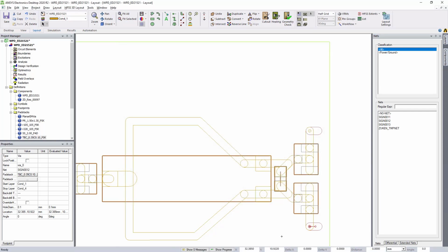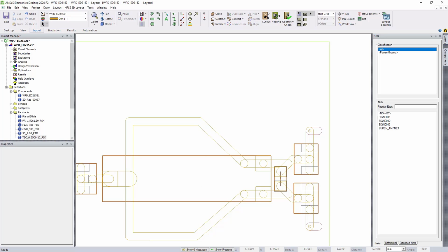As I mentioned, the layout engineer has full responsibility and authority on these elements within the design data. But as a simulation engineer, I want to provide recommendations to suppress the pads on conductive layer 3 and 4, or even try to highlight some way that maybe back drilling of the via may be required. So I'm going to change the particular vias to say they only span conductor 1 to conductor 2. So we have several different changes into the design, and I'm happy so far.